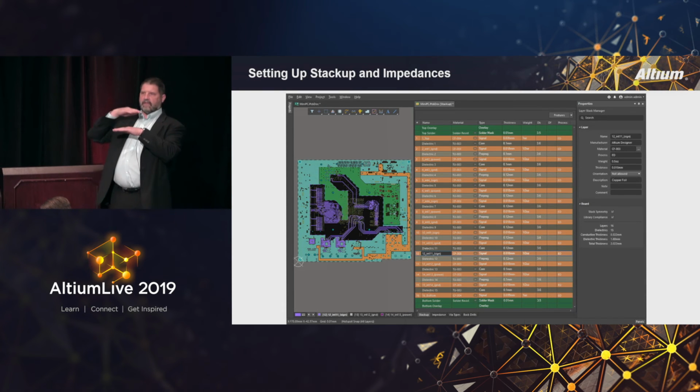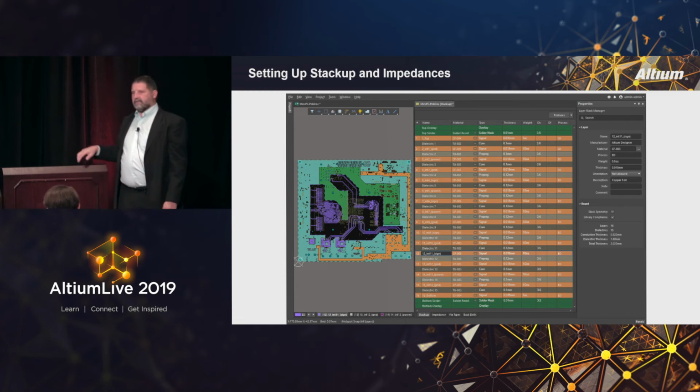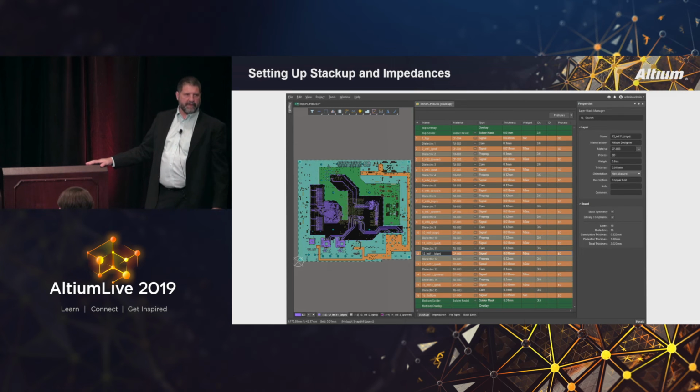Instead of referencing, like if your antenna is running on layer 1, don't reference it to layer 2. Cut out layer 2 and reference it to layer 4. Now that can be twice as large, and the accuracy of that antenna is going to be much better.